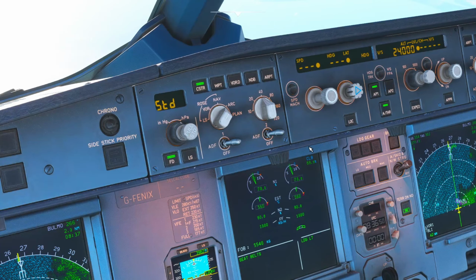In the center, you can find a button to adjust pilot 1 and 2, and the auto thrust system. A circular push button allows pilots to switch between different presentation modes of similar values. You can switch from the airspeed to a Mach number by clicking this speed Mach button.